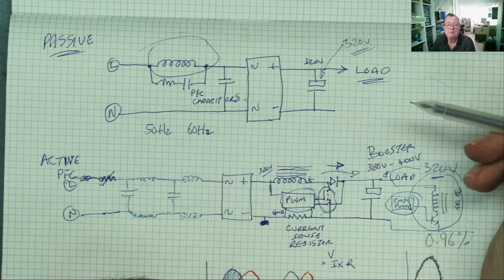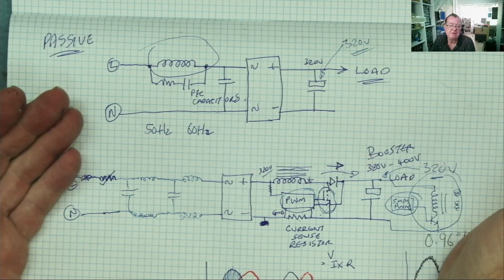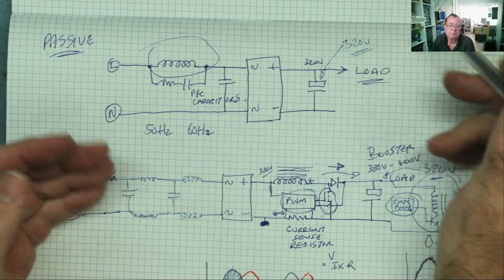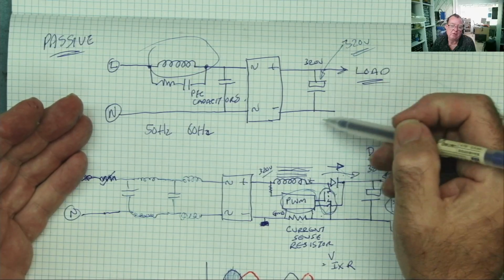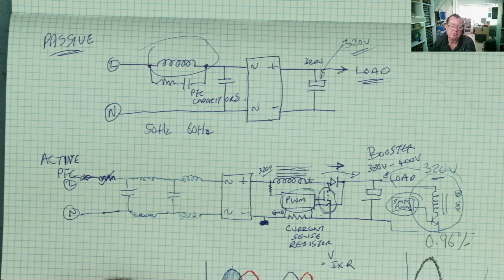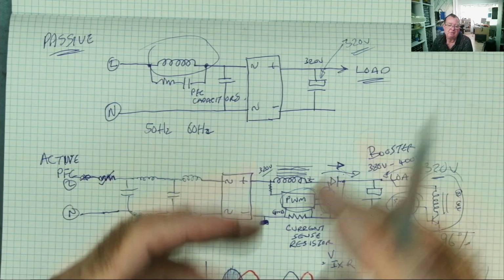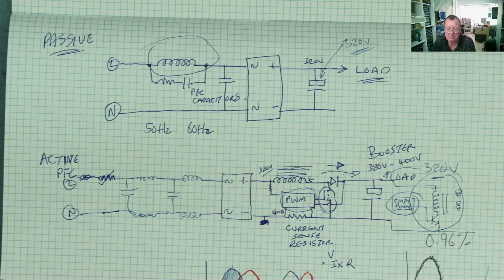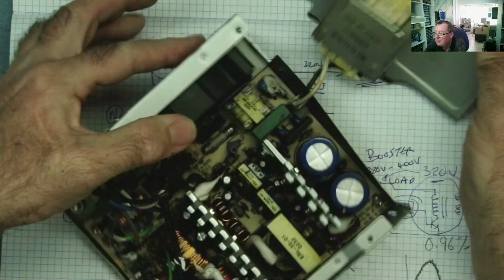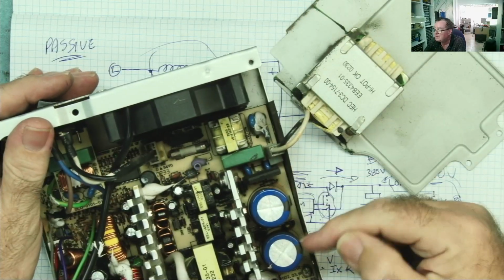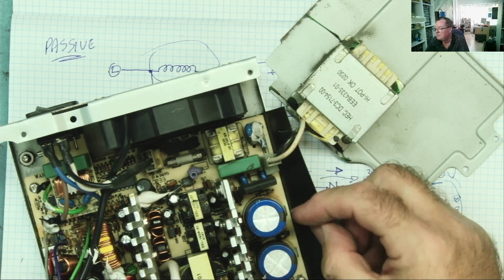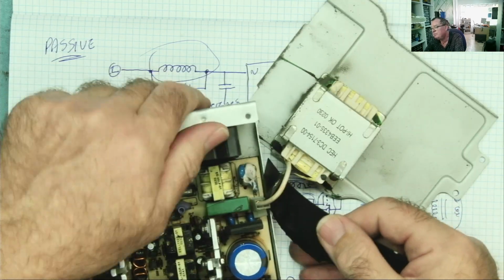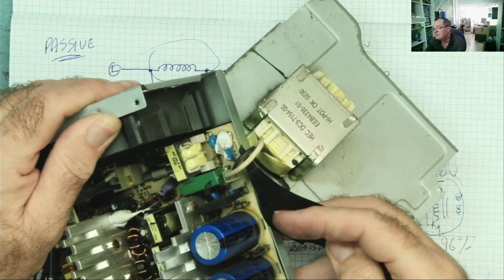What do we do? We come to repair the device, we plug it in, nothing happens, okay? We unplug it and we think straight away, have I got a high voltage in this capacitor or capacitors? So you need to get your voltmeter and measure to have a look. Where do you measure? Well, when you're looking at a circuit board like this one, the capacitors are here, and until you get the circuit board out of the power supply, you can't get under there to measure to see if there's any voltage.